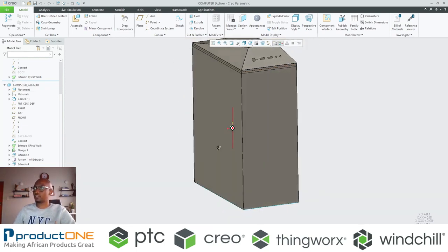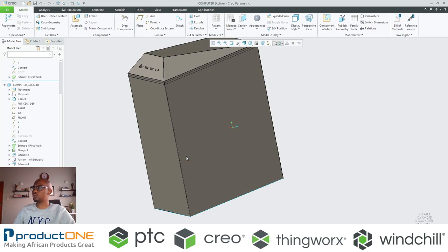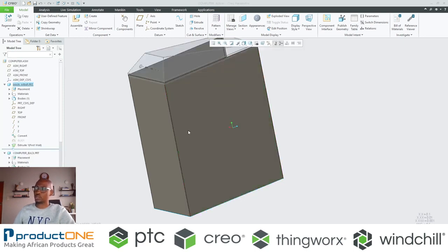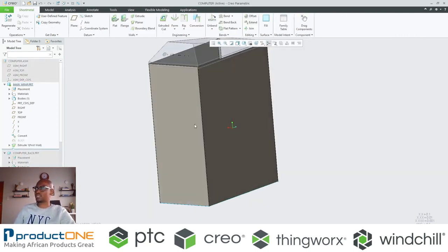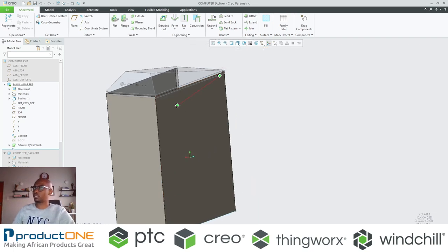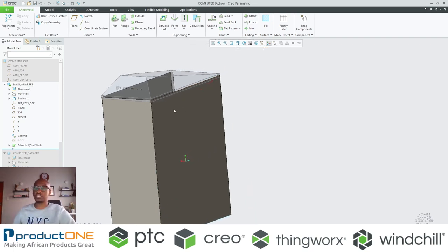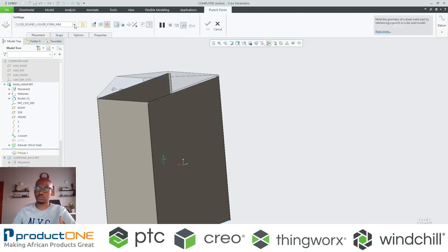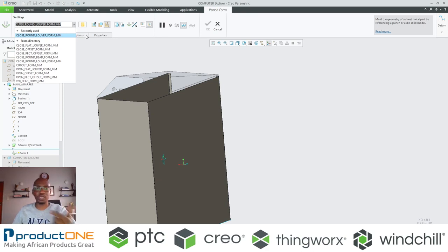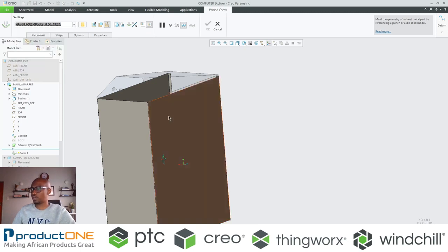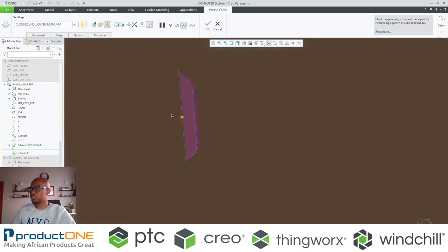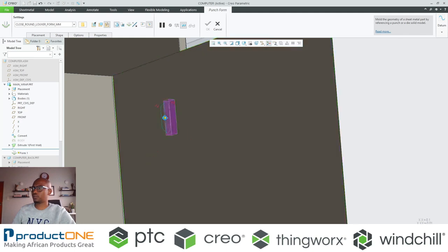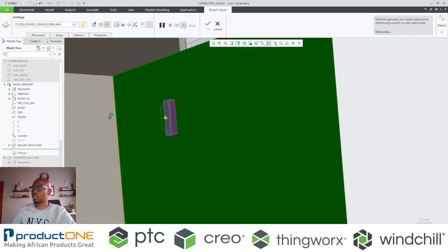So I think if we were now to move back into sheet metal, this is what I'm going to do now. Let's say for whatever reason, I require a little bit of ventilation also on the body of this. I can go about specifying what you call forms. There's numerous forms that one can choose from the library, and you can even create your own as well. So let's choose a louver. This is the louver that I've just selected here. In fact, let's maybe go the other way.